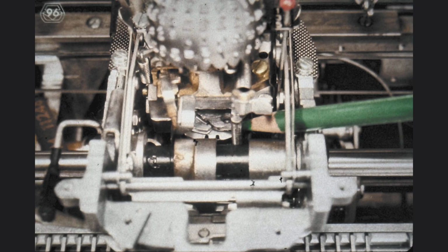We keep turning the element counterclockwise until we find the condition indicated here by the green pencil. Notice that the rotate tape is on its last turn around the pulley, and we must be very careful not to turn the element counterclockwise too far, or we will break off the tip of the rotate tape. Once we have arrived at the condition shown here, we again half-cycle a character so that the rotate detent can hold the element in this position.